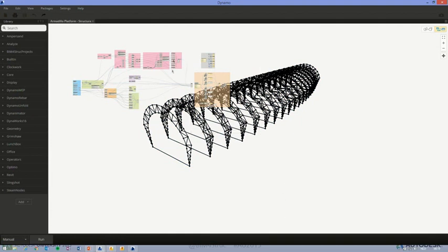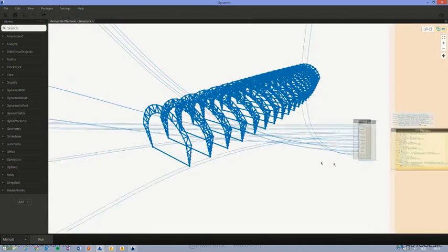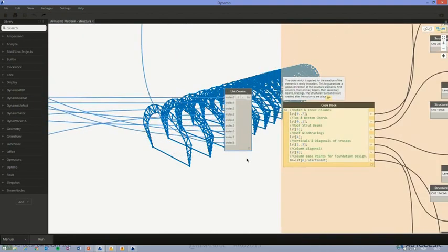So perform some list handling on it, and then you can take each second node or each third node or whatever, so that way it can help you to make diagonals, for instance. So let's see how this is done. There is a specific node called curve_point_parameter, which will take the curve and generate points along that curve. Okay? So if I select this group, show all geometry preview, there it goes. There we have all the points. Now the trick is just connecting these points.